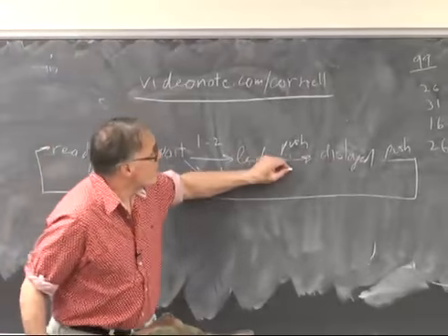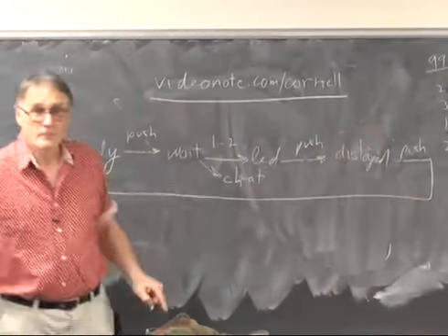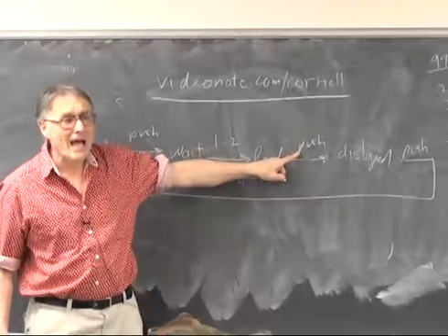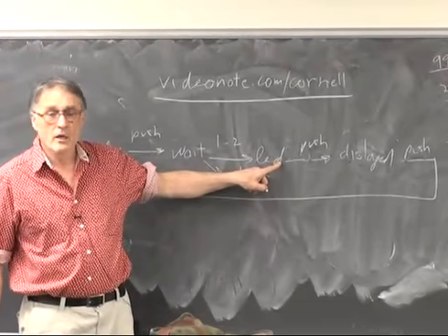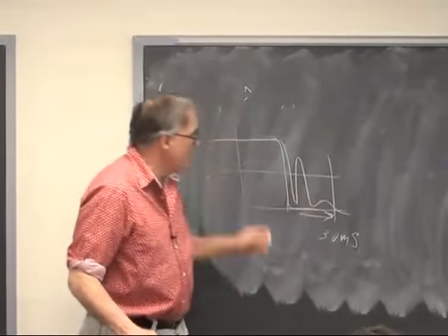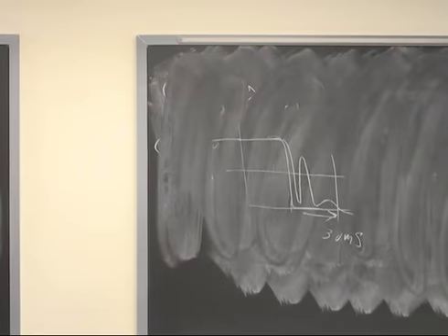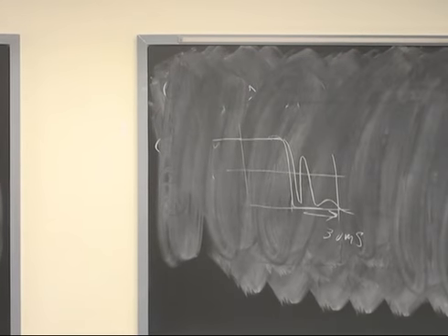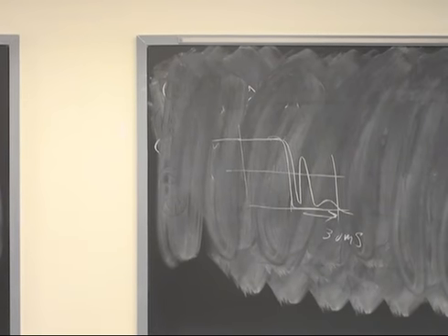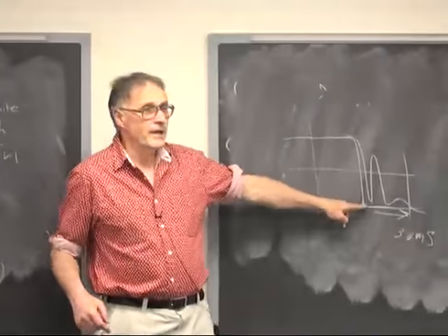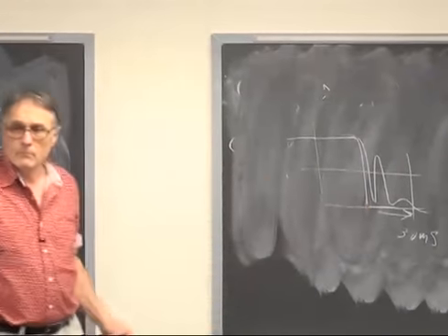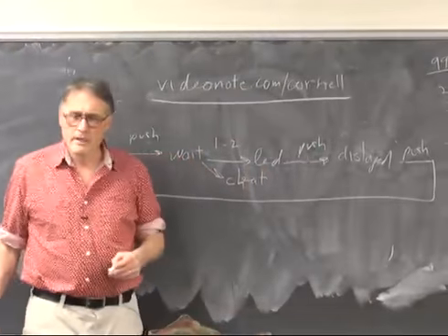You must debounce these two pushes. You must not debounce the button down here. Because if you were to say first strike of the button is here, but it settles here, then you would have decreased the reaction time of the human by an artificial 30 milliseconds. So here, for this button push, you have to take the first bounce of the button as the button down time. Any questions on that?